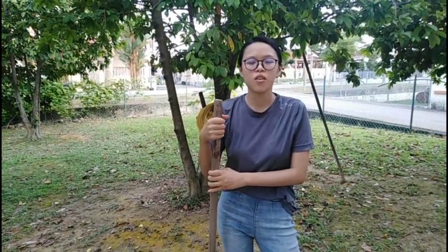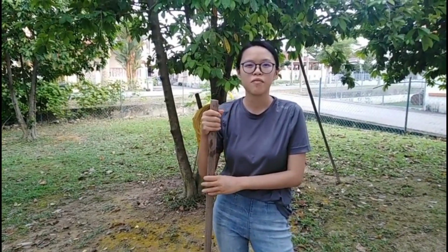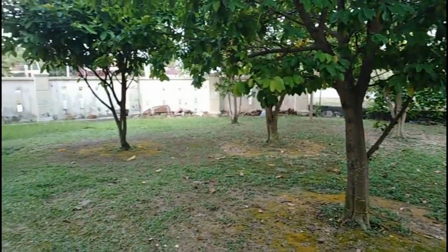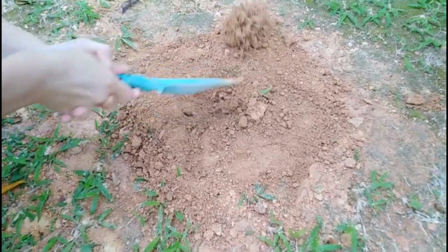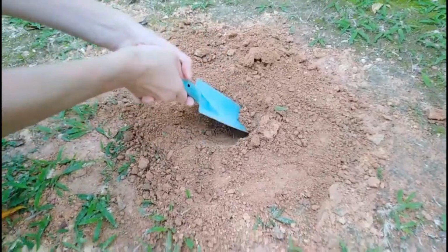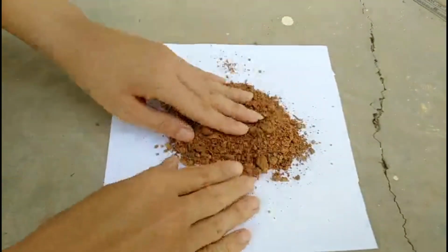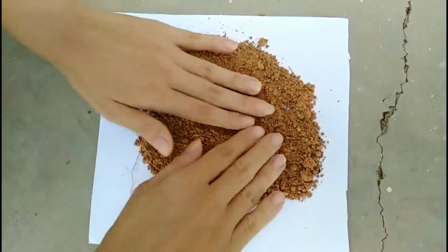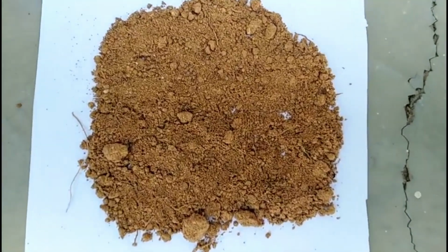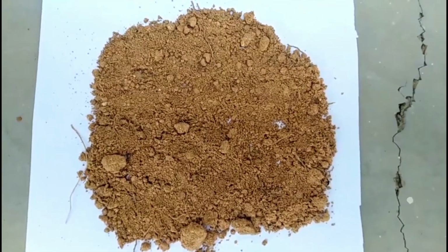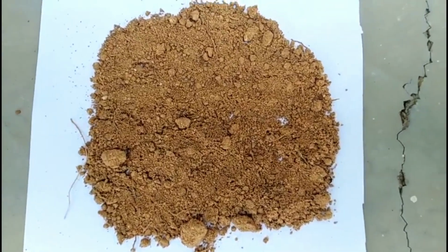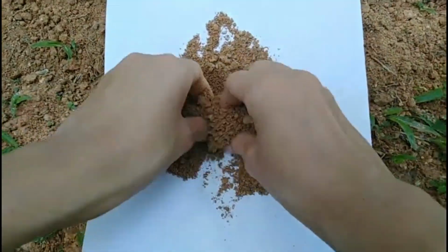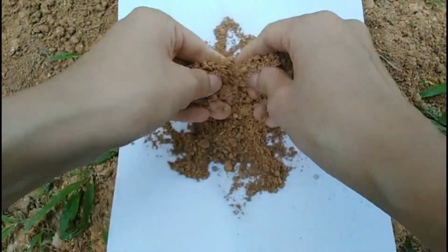In order to know the soil condition in my area, I conducted some soil physical testing in the field. Firstly, I dig a hole from the soil surface with a auger and take a sample. Next, I take the soil sample and spill it on a flat surface, and through visual inspection, I can get the idea that if the sample contains less than 50% coarse particles, then this soil is considered as fine-grained soil. After identifying the soil as fine-grained, I can conduct plasticity tests to distinguish clay and silt.